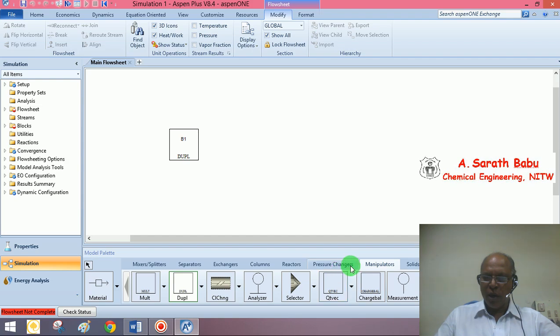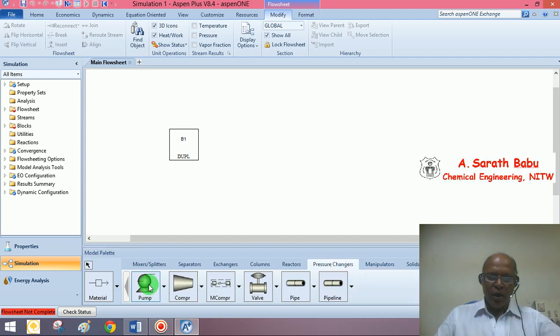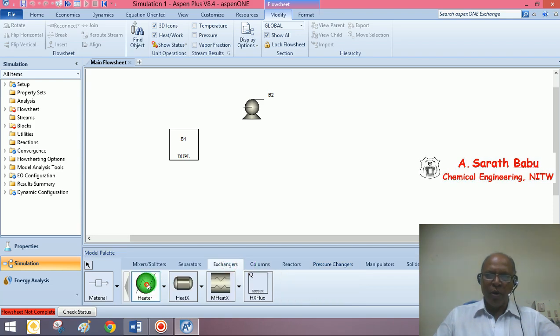Now as per the first option, first of all, sorry, it is pumped. The liquid ethyl benzene is pumped, thereby increasing the pressure from 14.7 psi to 73.48, followed by heating it to the required temperature. So I am going to use a simple heater because we are interested in calculating the energy balance, but not interested in actually going into the design aspects.